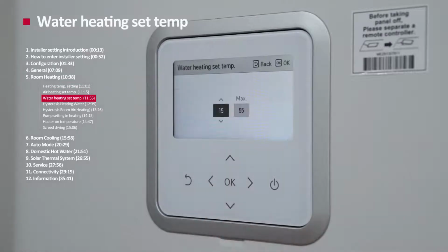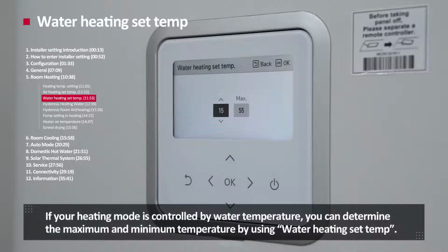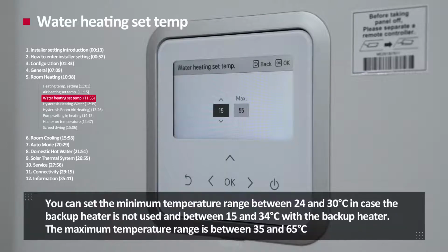Water heating set temperature. If your heating mode is controlled by water temperature, you can determine the maximum and minimum temperature by using water heating set temperature. You can set the minimum temperature range between 24 and 30 degrees Celsius in case the backup heater is not used, and between 15 and 34 degrees Celsius with the backup heater. The maximum temperature range is between 35 and 65 degrees Celsius.